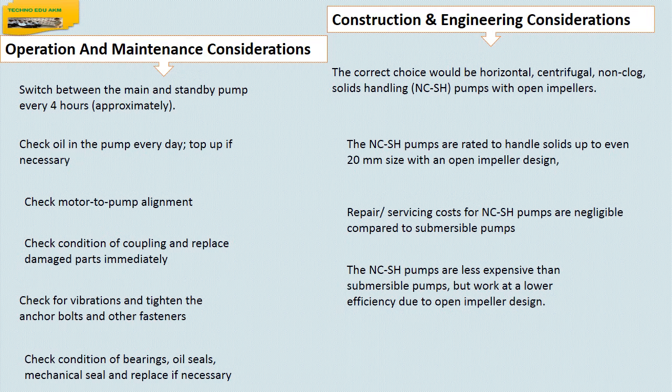Construction and engineering consideration: the correct choice would be a horizontal, centrifugal, non-clogged solid handling pump with open impeller. The non-clogged solid handling pumps are rated to handle solids up to even 20 mm size with an open impeller design.